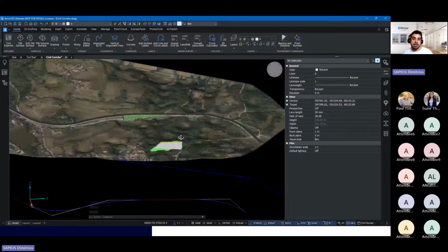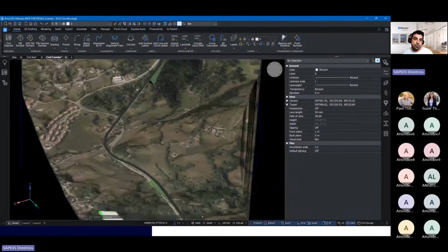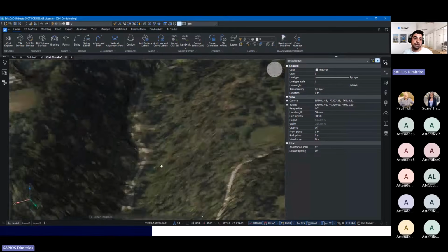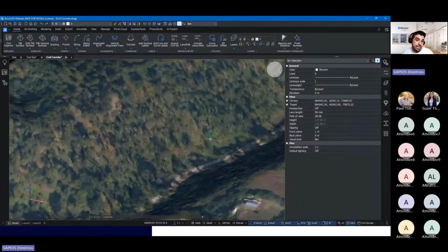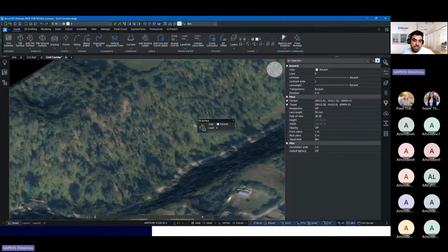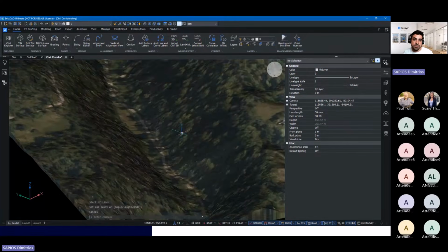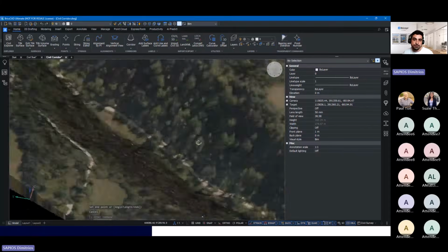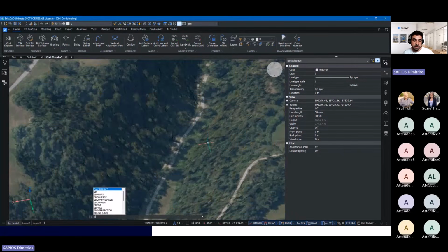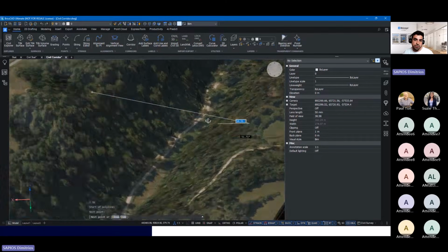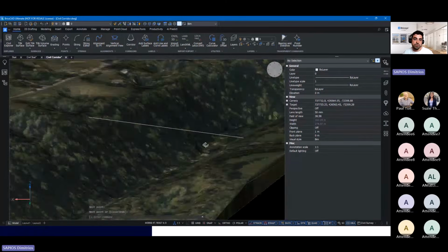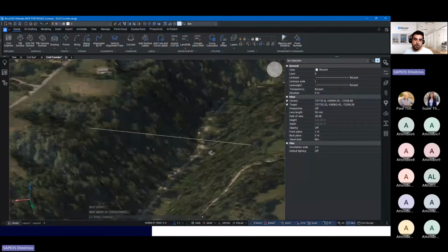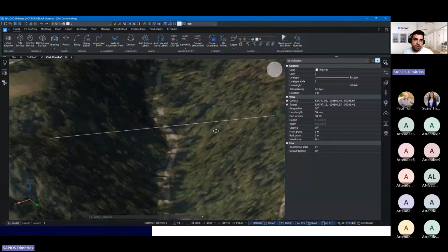And we can, of course, create interesting gradings with other entities, like a simple line in this case. Let's create a nice little dam along this canyon, shall we? So let's go ahead and create a 3D polyline from this edge to the other, connecting those two hills.